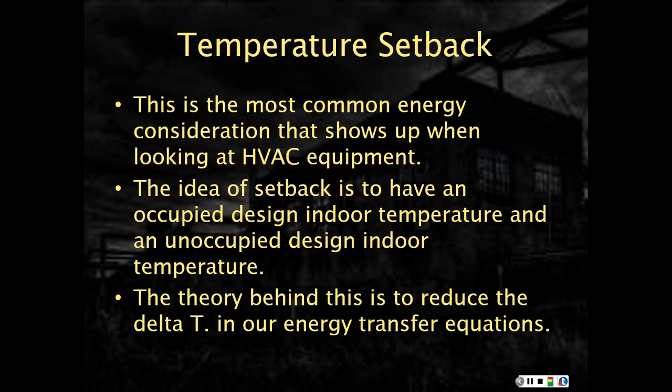First thing I want to look at is something called temperature setback. The reason I'm looking at this is this is one of the more common considerations that show up when looking at HVAC equipment, and especially the federal government, if they're paying for an energy audit, they'll usually give you a suggested list of things that they want you to look at. The idea of temperature setback is always at the top of the list. So if you don't know how to do any other thing, having a look at temperature setback and at least when it's applicable and what the impacts are is a valuable tool.